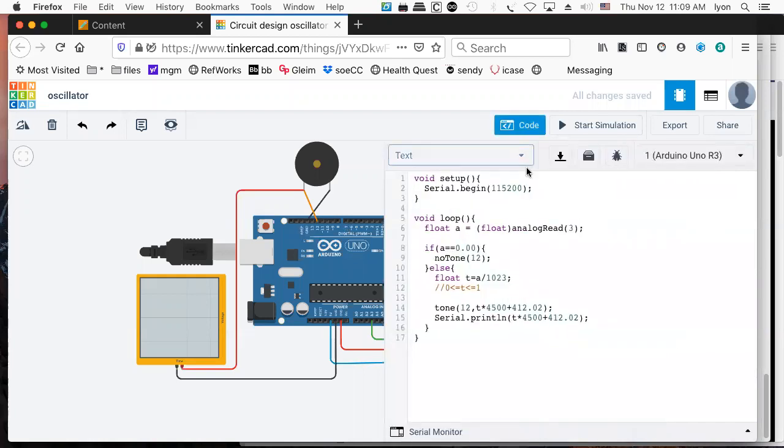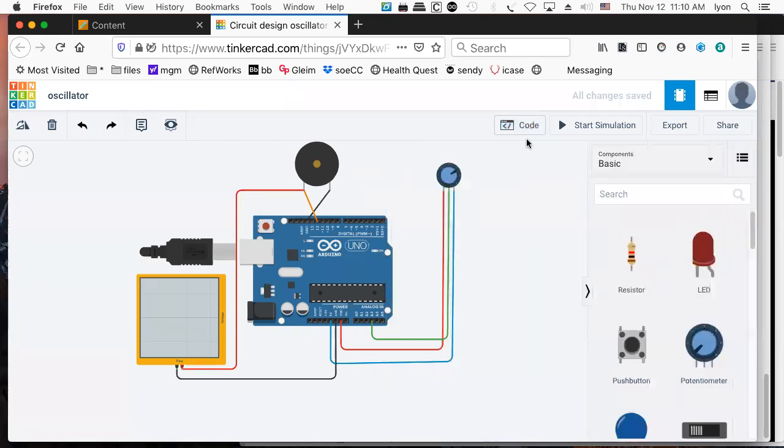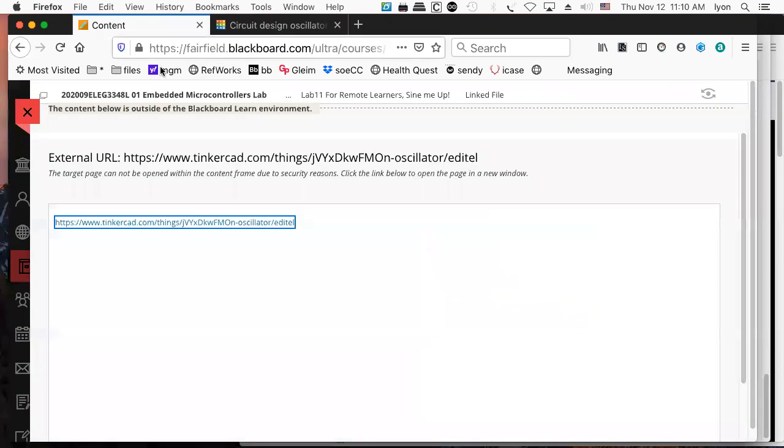What we're doing here is quite simple, really. We're reading from the analog input. We're normalizing the analog input, which goes from 0 to 1024, into a variable we're calling a parameter, and that parameter is t. Then t is being used to create this tone, so we're essentially modifying the signal a little bit with t. So that's it. And what I wanted was to have you guys do a filter.